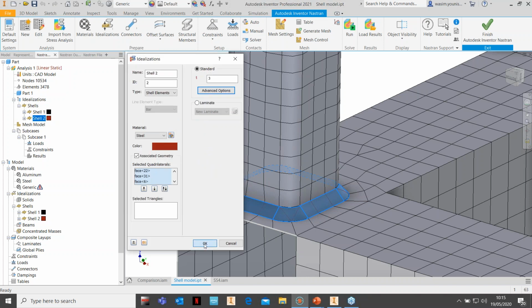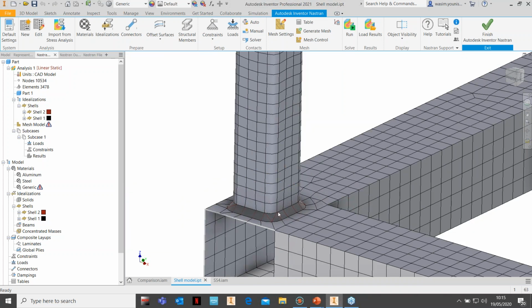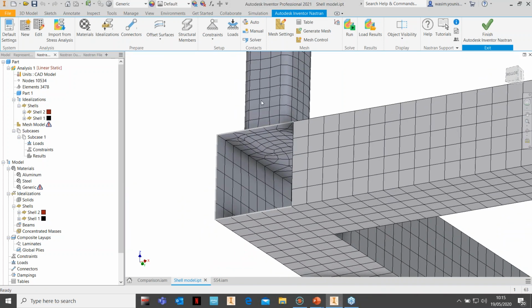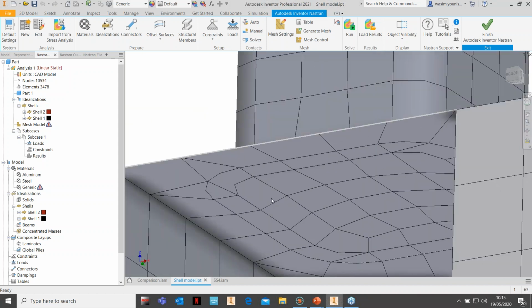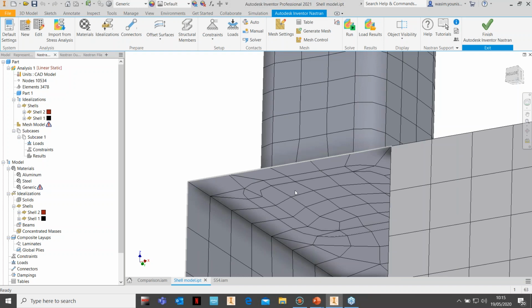Now, that's fine, but you have to be aware that that box section is in contact here as well. So you actually get extra stiffness, so you have to be aware of that. So you can see straight away, adding fillets or adding welds can actually create more work, and the real question becomes, is it actually worth the effort to get accurate results?